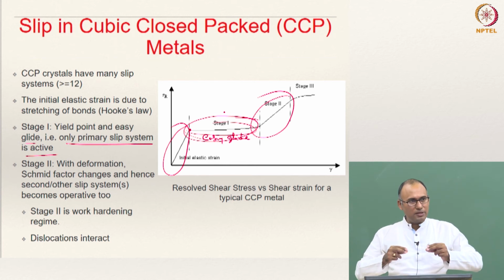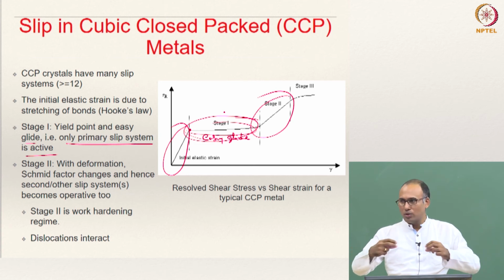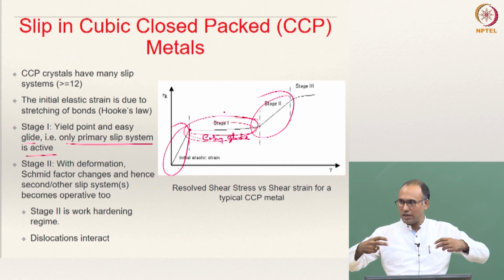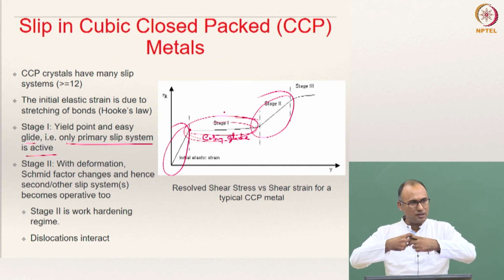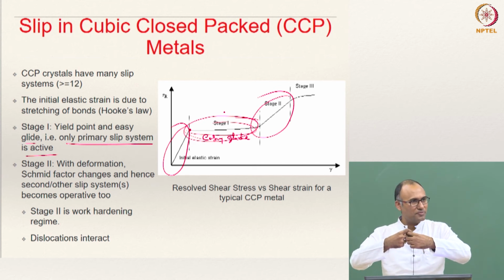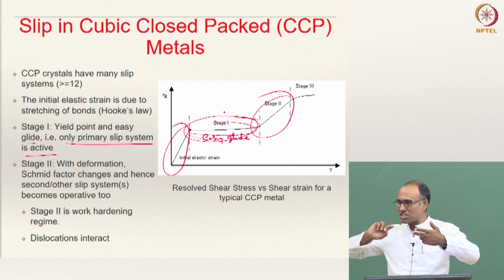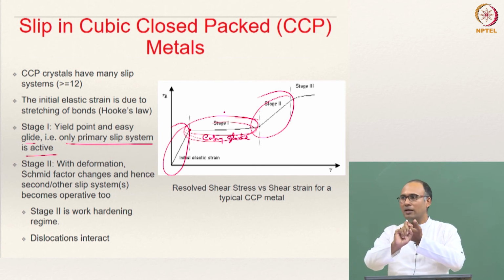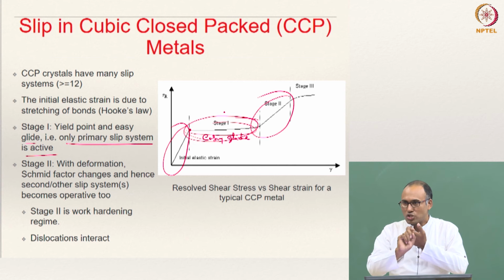You can create a hump here and then on the other side and then move, and then this guy is in one orientation and this guy is in another orientation, and they sort of entangle, right? And then they provide resistance to further motion. That means these dislocations are interacting and they hinder the dislocation motion.